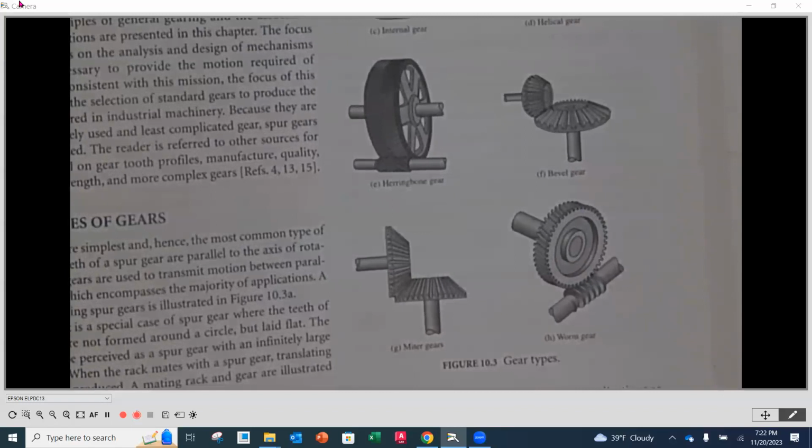We're going to be looking at the spur gears in just a little bit, but backlash is going to be, if you would, the slot between the two gears, and it's how accurately those gears are created. And sometimes when you're changing direction from one way to the next, and back the opposite way, you're going to have a little bit of a gap in there, like an air gap from when you were going in one direction. There's going to be a gap, and then you're going to engage in the opposite direction, and that's called backlash.